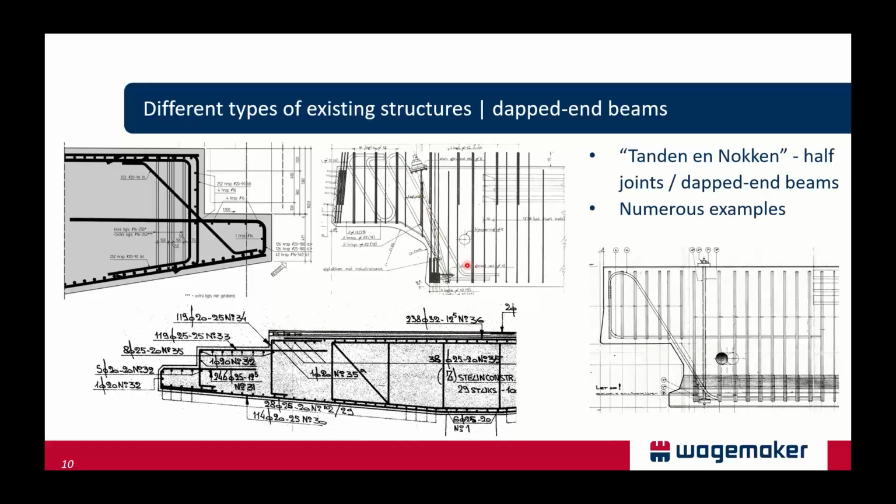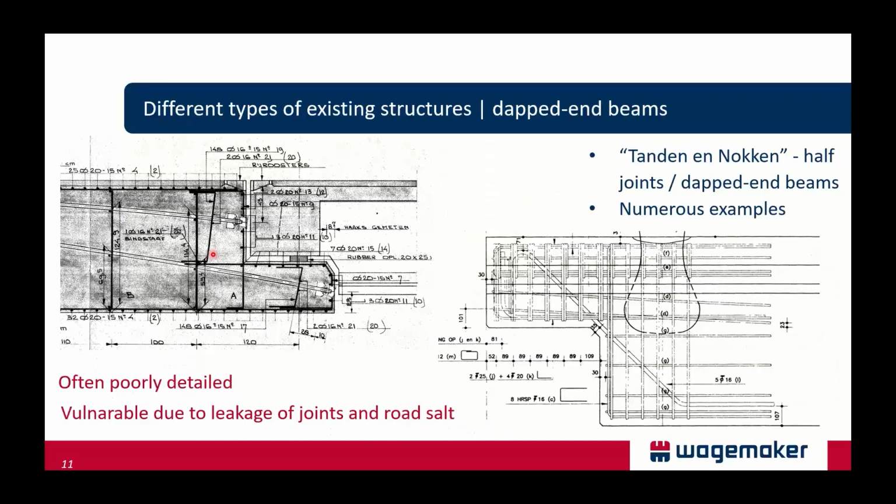This is a typical strangely bent bar, but it was used back in the day when they designed this kind of structure. And we notice that the reinforcement ratio in the beams is relatively high. This shear-prone zone is full of stirrups, while the supporting structure usually exhibits less reinforcement.